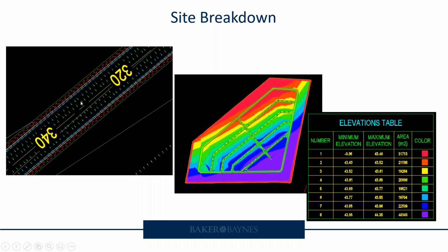So when you apply your super elevation or your crossfall, you will see something of this effect where the site is sloping towards here, and we've got the road sloping in the opposite direction, so that the water drains and channels along this side quite nicely. So that will give you a bit of an understanding of the procedure that I applied here.